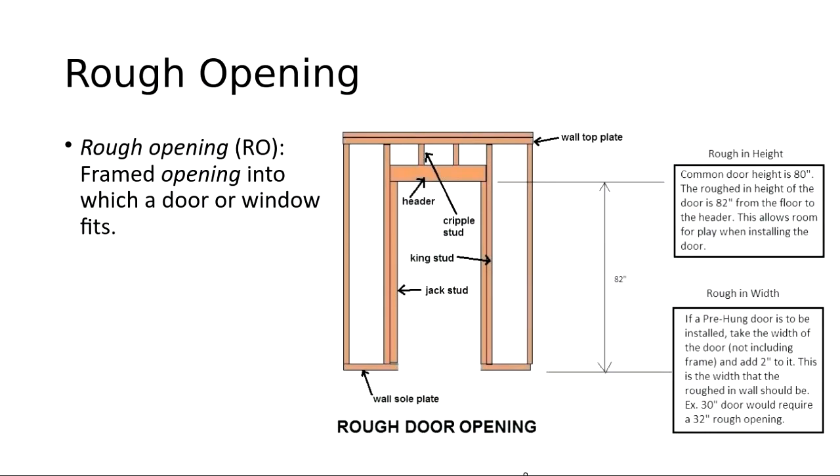And then you install the door and window in there, and you put shims in there to hold it in place. And the reason you make it wider is if you're a little crooked or something, you've got some play to get it in. You'd never make it the exact same size as the window.